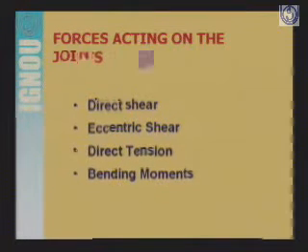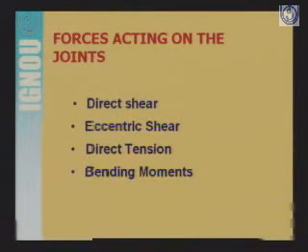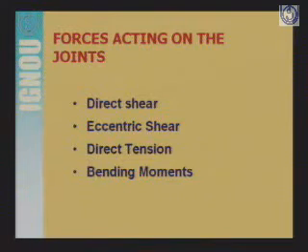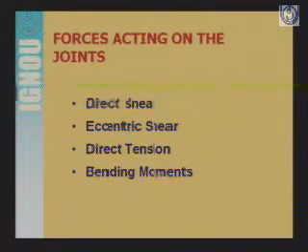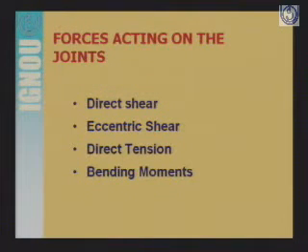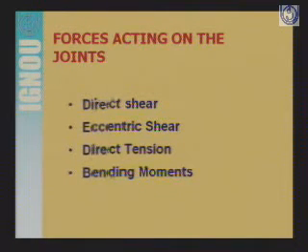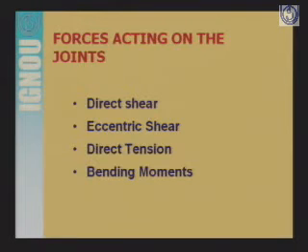In this case, the point of action of the force does not coincide with the center of gravity of the connection. The point of application is away from the CG, so there is an eccentricity of the load with respect to the CG of the connection. That is why we call it eccentric shear. Third is direct tension, in which tensile forces act on the member, and fourth is bending moment.